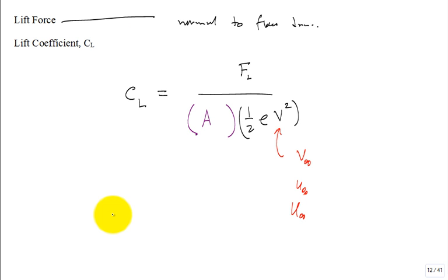And aircraft are very streamlined, and they have things that are wings, true? So should we look from this perspective out here to look for an area? Or should we get way up here and look that way for the area? From the top. We should look from the top. And so now that area, there's some different names for it, but planform area. Did I make up that word? No, I did not make up that word. Planform area. So it's that, from a distance looking down on the wing, it's that silhouette area.